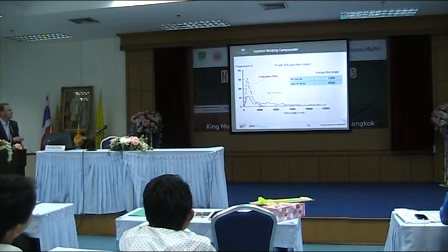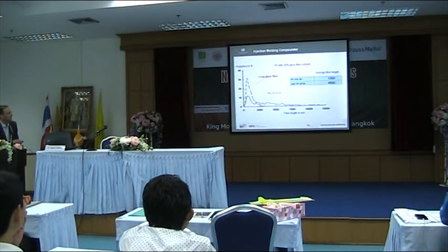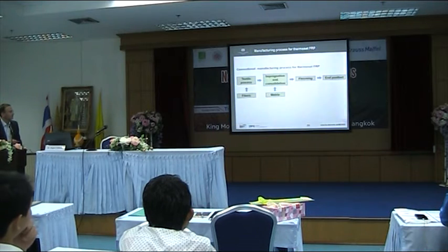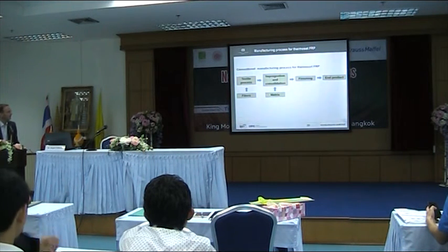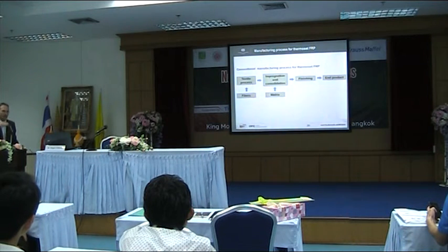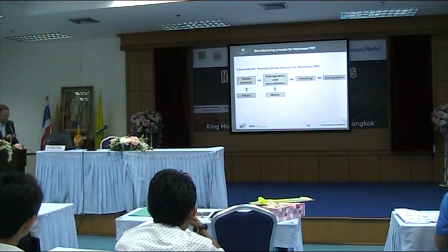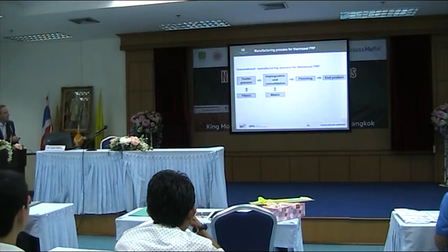So you see here the average fiber length. When you use really long fiber, you have an average of around about 1 millimeter, and with injection molding compounder, you can reach something about 4 millimeters. Okay? So, now, when we want to have longer fibers, with injection molding compounder we can reach something a little bit higher, but we cannot use endless fibers. Now, looking at conventional thermoset, you have fibers, then you make a textile process.